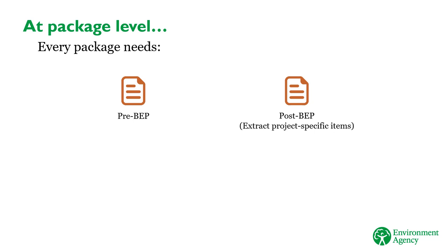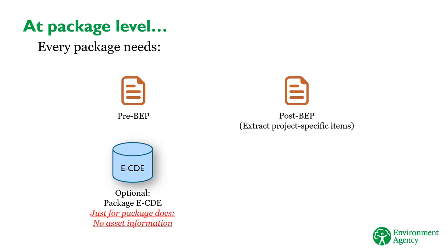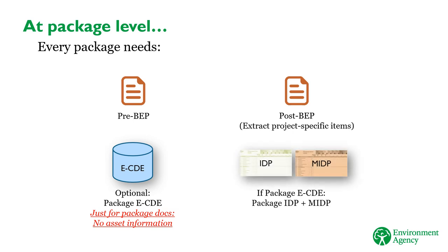You also have the option to create a package-level CDE. This must only be used to help manage the package. Anything relating to the projects or containing asset information must be transferred via project CDEs. If you decide that you want a package CDE, then you'll also need a package-level IDP and MIDP. And you need to identify someone who is involved with the package to manage all these things. We would recommend not creating a package workspace unless you're sure you really need it.